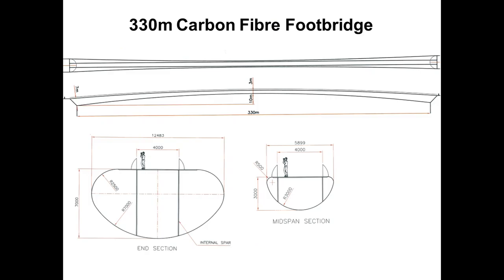It's an arch. I imagine it's part of an ellipse, and in one of your data sheets you will see that there are some clues about the best ways to span using pure geometric shapes. But I'll just quickly emphasize that if you cut sections through a cone, you'll find all the best shapes pretty much. So you will find ellipses, you will find the parabolic curves, of course you'll find the circle or semicircle, all of which work very, very well, we know, structurally.